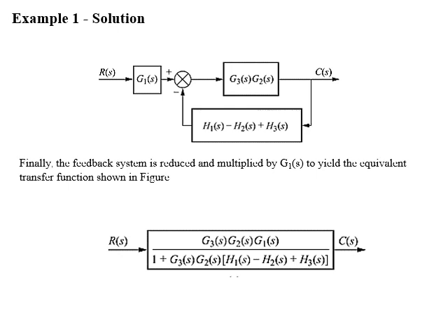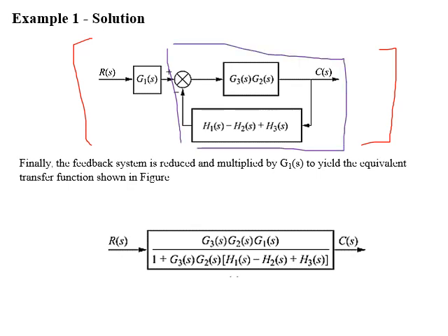Now we recognize that our system is in feedback form. So applying the rules of feedback form, we get our equivalent transfer function. Now after reducing, G1 will occur in cascade form with the feedback form subsystem. So the equivalent system will be a product of G1 of S and the equivalent system from the feedback system. The equivalent system is shown in the second figure of the slide with input R of S and output C of S.